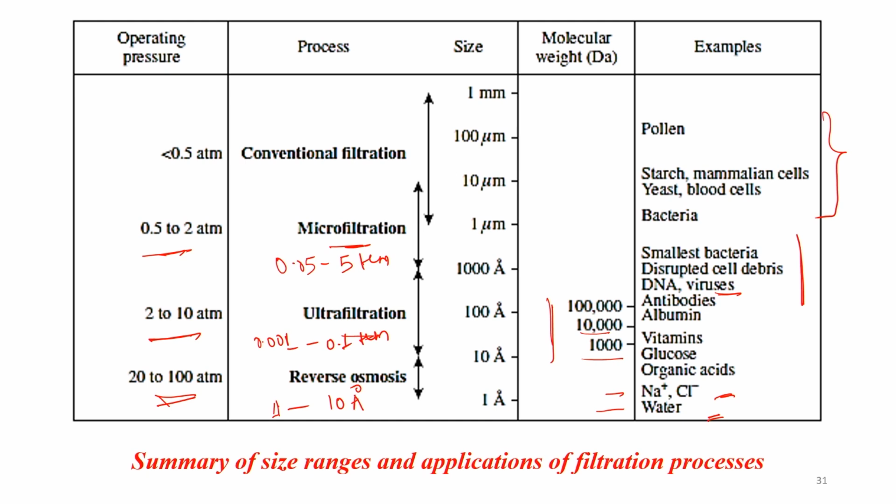Membrane filtration requires the operating pressure as a driving force. So, this may be one operating cost. In addition, the cost of the membrane itself is a major challenge in the case of membrane filtration. Further, as we have seen, there is concentration polarization as well as membrane fouling. So, it is very much needed to design anti-fouling membranes, so that you can improve the life of these membranes. So, with this I will stop here.